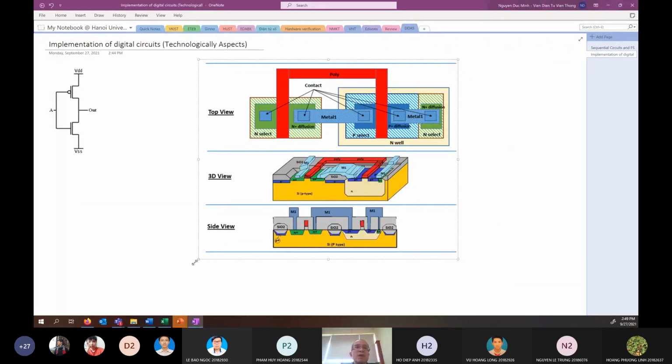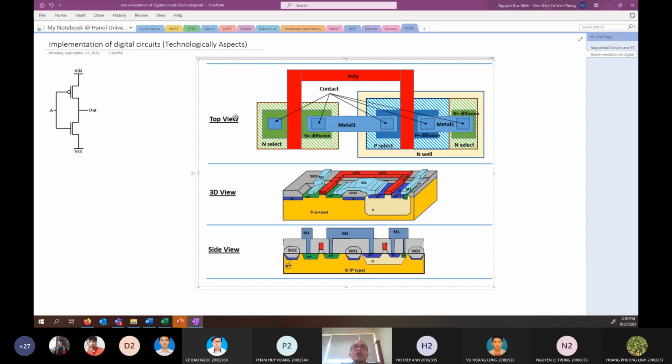So now the ASIC means that you connect a lot of gates, the NOT gate, the NAND gate, the OR gate, and so on. You put them into a very dense area, and then you manufacture or fabricate it on a silicon surface, or you call it a wafer. So when you put all the transistors of the logic gates and flip-flops into a very dense area on the wafer, you have the ASIC implementation of the circuit. You got it? You understand?